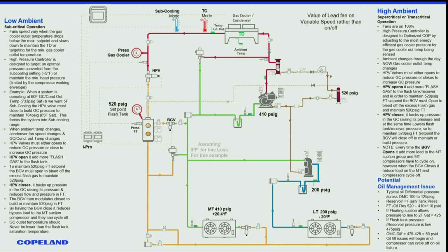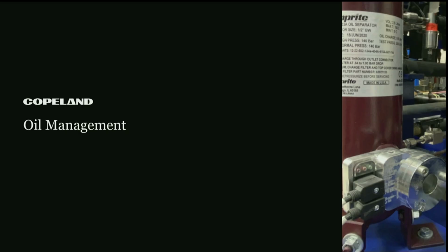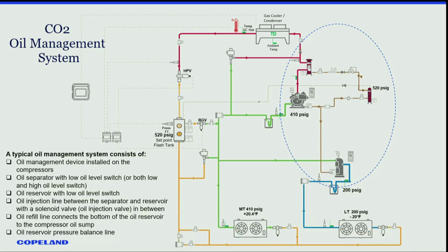And you might be wondering, it's asking for oil, but it's alarming because it can't fill it fast enough. What's going on? I don't understand. Why all of a sudden is it not filling fast enough? Then you have to go back and figure out, did something happen to my flash tank pressures that could have influenced my receiver pressures? Did something happen to my suction pressures as well? Everything in combination adds up to not enough pressure to feed the compressor fast enough in 120 seconds. Those are things to ask yourself when you're going through it.